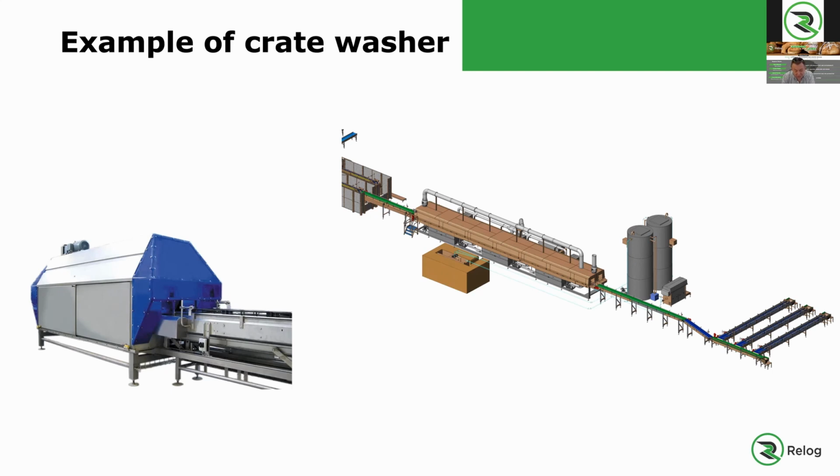We're doing a project at the moment where the water that comes out of the clean water rinse is what you're putting in on a continuous basis. So the spill-off from our crate washer feeds our truck wash, which means that we're using zero water in addition for the truck washers. Okay, and that just gives you a total water balance. And if you can use rainwater or recycled water for that, you're actually on zero potable water use. And South Africa is an arid country, so we need to be thinking about that in a lot of ways.